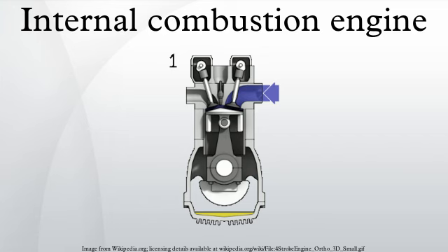Engine cooling. Cooling is required to remove excessive heat. Overheating can cause engine failure, usually from wear, cracking or warping. Two most common forms of engine cooling are air-cooled and water-cooled. Most modern automotive engines and larger engines are water-cooled, while most power tool engines and other small engines are air-cooled. Some engines also have an oil cooler.